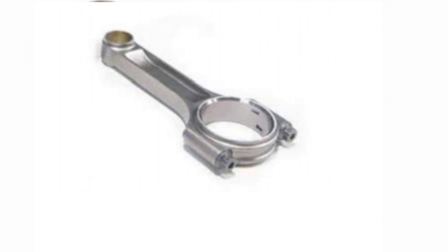Connecting rod. It converts the reciprocating motion of the piston into circular motion of the crankshaft in the working stroke. The smaller end of the connecting rod is connected with the piston by the gudgeon pin, and the bigger end of the connecting rod is connected with the crank with a crank pin. Special steel alloys or aluminum alloys are used for manufacture of the connecting rod.